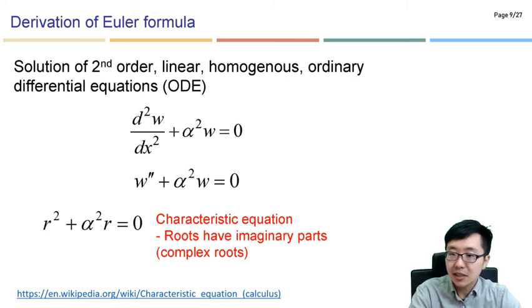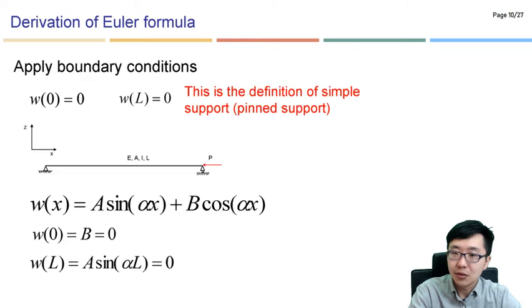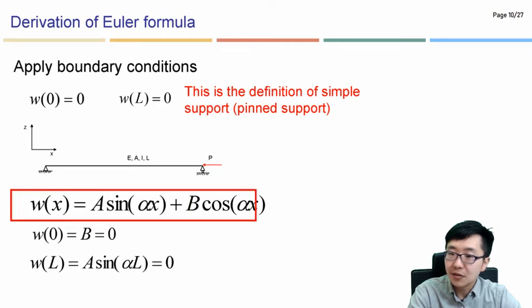And basically it is not difficult. W is assumed like this way, and then set the boundary conditions, and then substitute all the conditions. So two unknowns, two boundary conditions used, and then we can determine A and B so that we can finalize these deflection functions. So detailed procedures are here. So what we have is this function now.